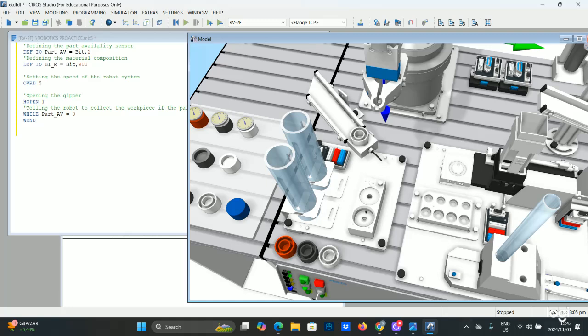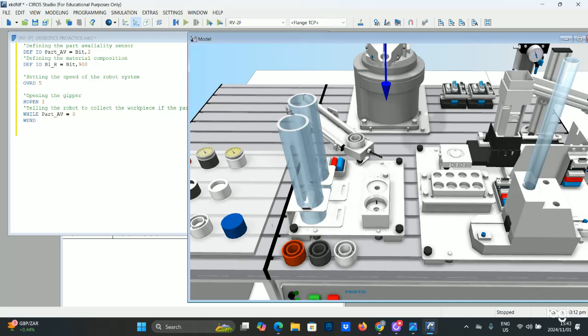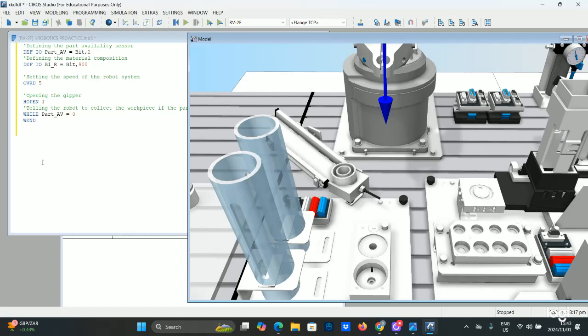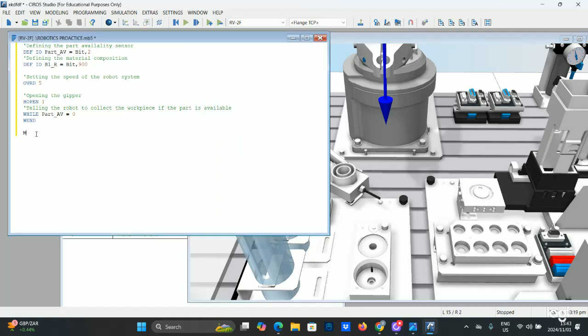So now let's say I'm trying to move to this workpiece to grab it. My first move, I'm gonna move straight to the workpiece. So I'm just gonna say first MVS to that position, here it's P1, at a maintained position of -30.